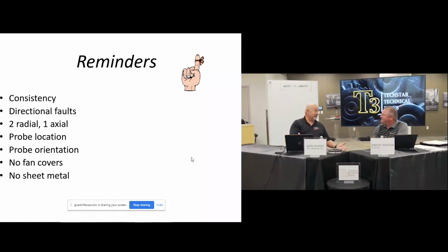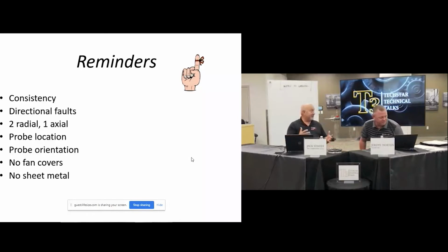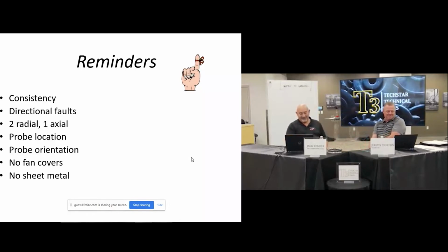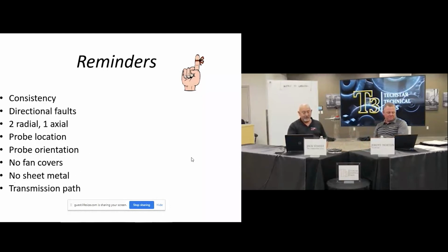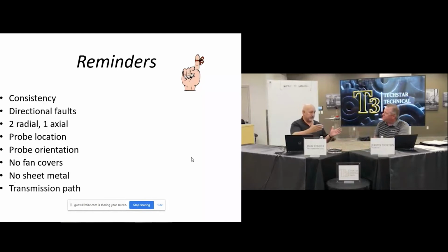And then you walk out and go, it's a coupling guard. Why did you take vibration here? Some great coupling guard vibration readings, but that's right. Very little bearing, or we got vibration here, but it's an alarm. Yeah, so, makes sense. Transmission path. You want to get as close to the bearing as you can. A big, thick piece of metal there in a casing is going to be a little rough to get good data.